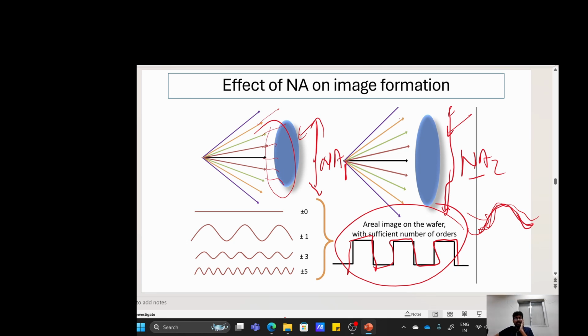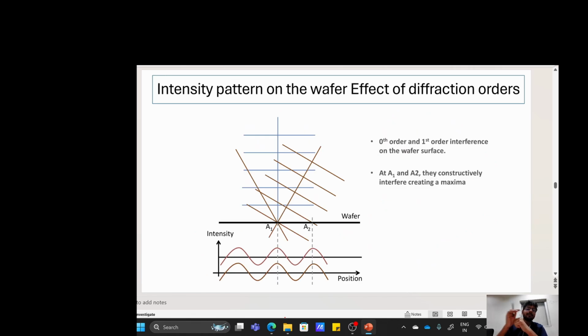That is not desired, because there will be a problem in lift off: if there is a wedge, most of the metal gets deposited because there is no undercut. There are some other things that we will see when we do the etching process. In that you will understand why we do not need a wedge kind of profile on your photoresist. So let us move forward.